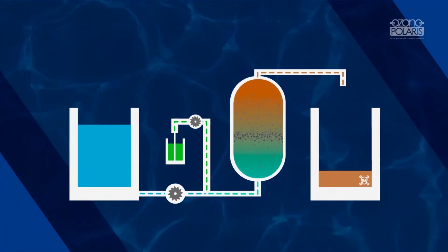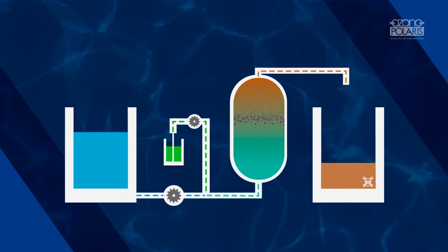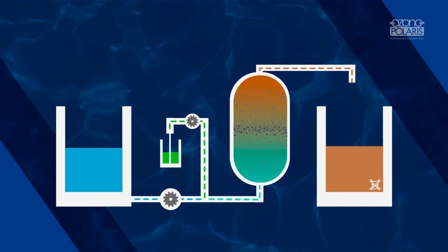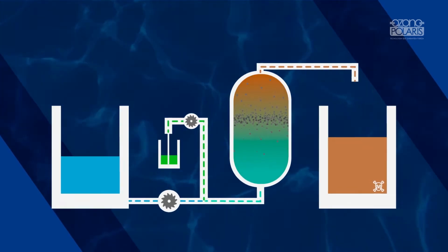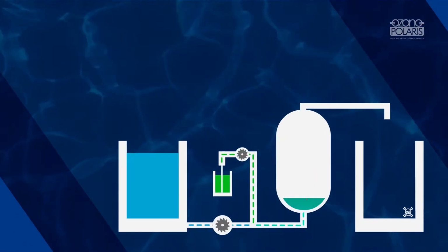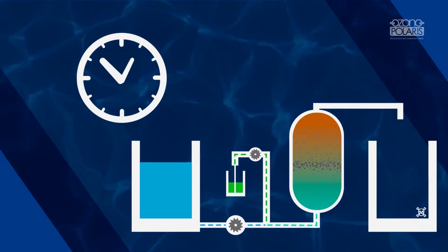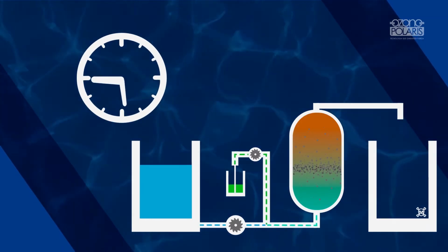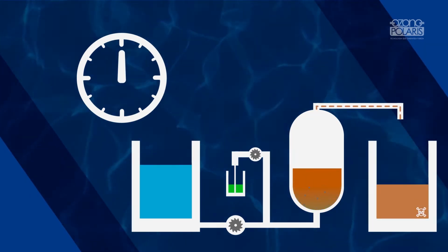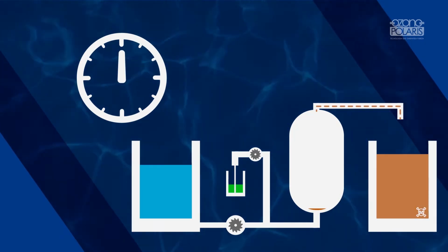There are some partial solutions. Several researchers have shown that activated carbon can be chemically regenerated, in other words, reactivated. For example, by a heated alkaline wash, by an acid wash, or by washing with a solvent. However, chemical reactivation is rarely used because of the cost of the chemicals and the treatment of the wash solution. Soaking the carbon in chemicals uses less water but is time-consuming and inefficient.